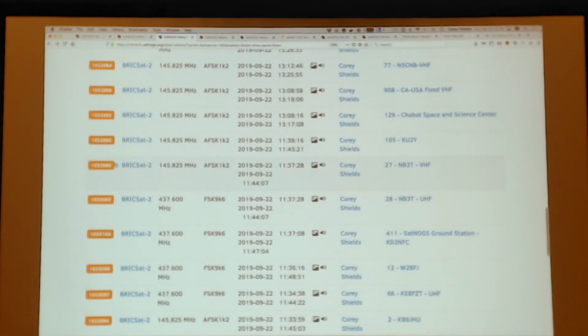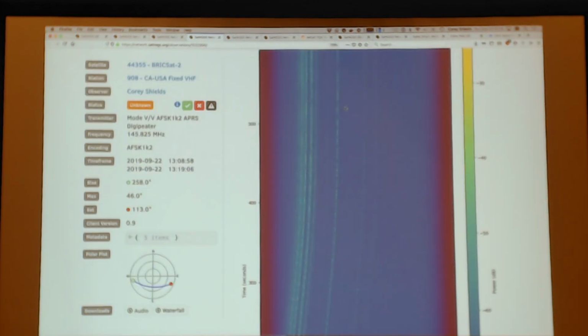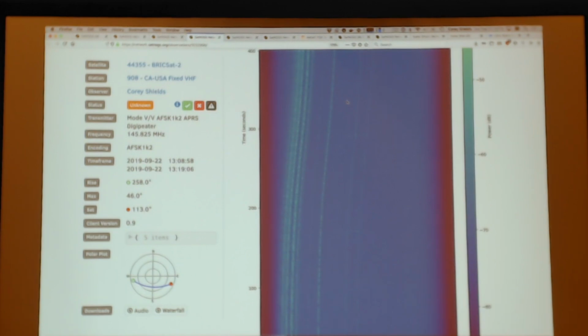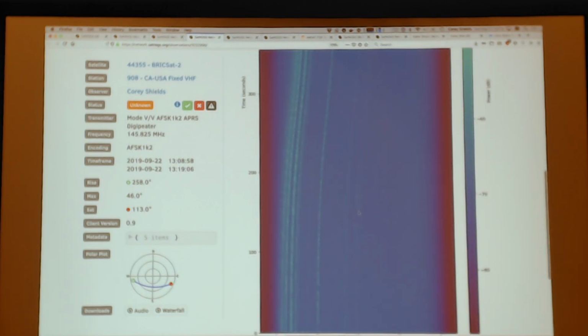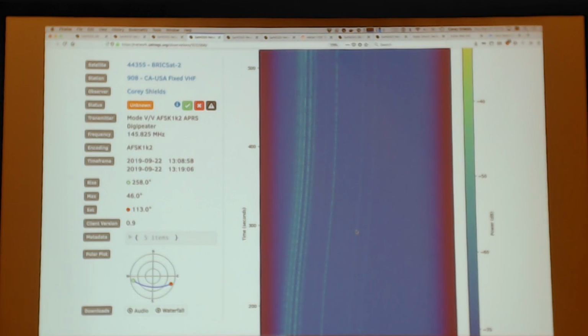The one I just had, I think it was right here. This has a rotator on it, and the motor and motor drivers aren't shielded. This will leak in, and you might see this RFI. These look like they're Doppler corrected, right here in the center. They look like they're probably packets, but we didn't decode them. Like this right in here, and here's another one up here, and another one down here. So this is one where, in your case, I would download this, pipe the audio through the UZ7HO high-speed modem, and see if that decoder can actually decode it as well.